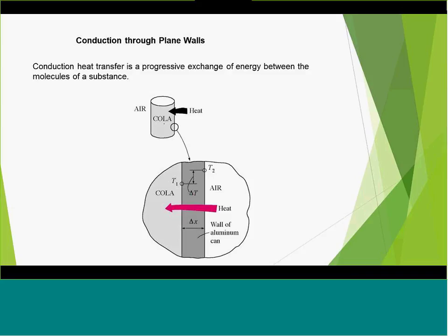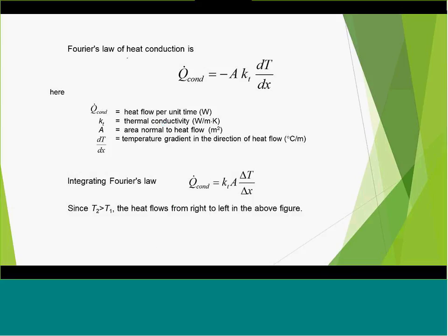Means when you have conduction, the law of heat conduction, in the equation, don't worry, it's given. So the heat transfer for conduction is negative kA dT over dx, the differential of temperature towards the thickness of the boundaries. Basically you're going to have the heat flow per time. You have the thermal conductivity. For every material, we're going to have different thermal conductivity values.